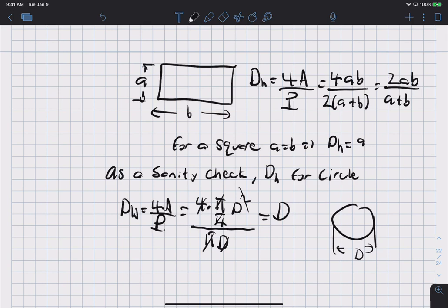And so essentially, if you have a non-circular duct, as a first order approximation you can use the formulas for a circular duct for the friction factor and everything, but base the diameter that you use in the Reynolds number on the hydraulic diameter. And so that wraps up the theory for Chapter 8, and in the next lectures I'm going to go over a bunch of examples.